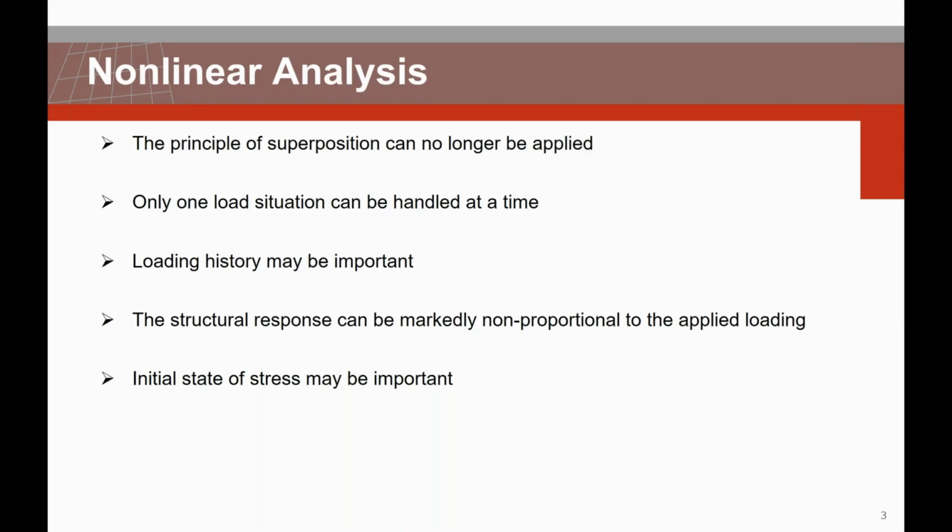Loading history may be important. For example, the nonlinear behavior of a vessel, which is first heated and then pressurized, is quite different if the loading sequence is reversed. The structural response can be markedly non-proportional to the applied loading, and also the initial state of stress may be important.